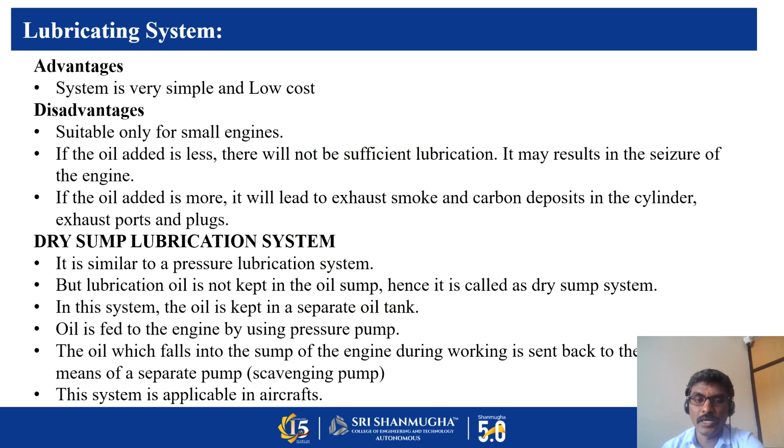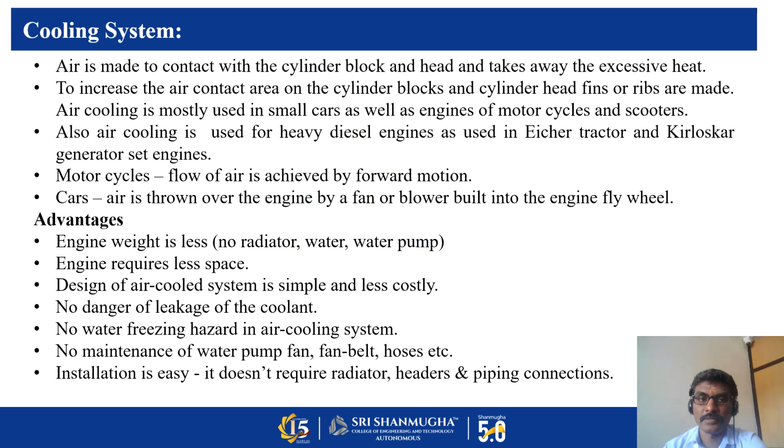It is similar to a pressure lubrication system, but lubrication oil is not kept in the oil sump, hence it is called a dry sump system. In this system, oil is kept in a separate oil tank. Oil is fed to the engine by using a pressure pump. The oil which falls into the sump of the engine during working is sent back to the engine by a separate pump, the scavenging pump. This system is applicable in aircraft.